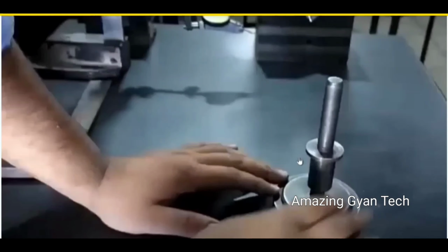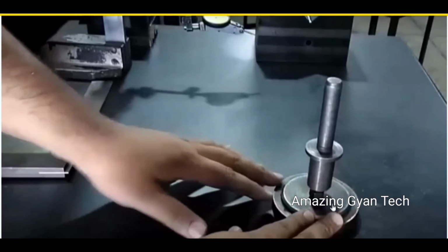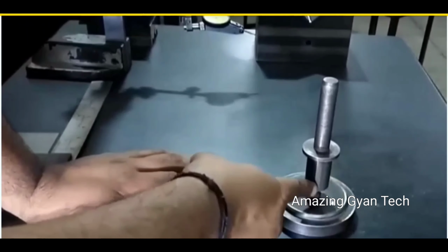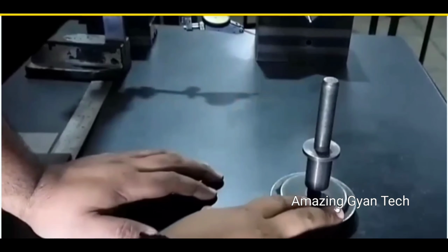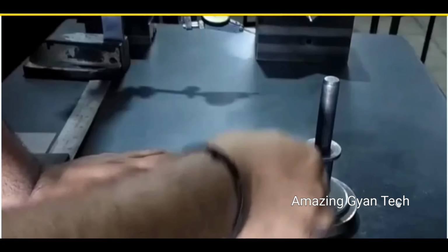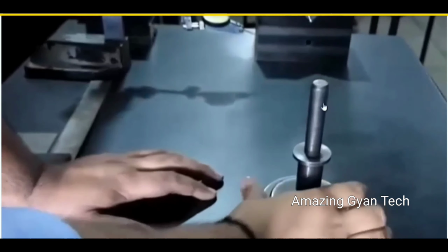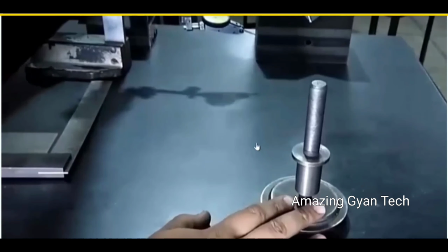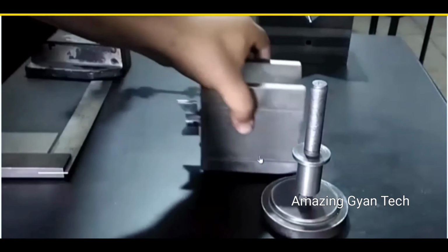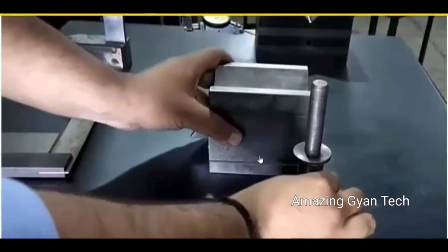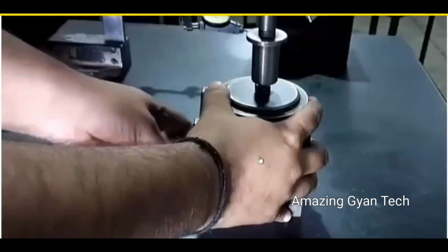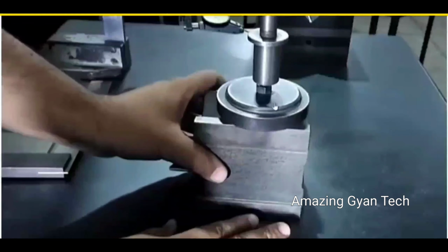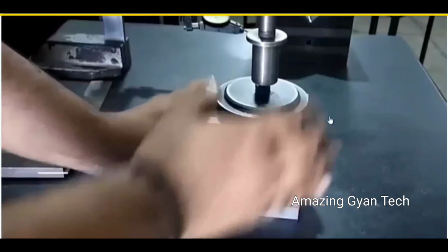If you look into this video, they are going to check the perpendicularity with respect to the bottom face towards the vertical rod with respect to the bottom diameter. For this, they are going to keep this component on the V block. They will attach it to the V block and keep it on the surface plate. The V block, as you know, is going to be a 0,0 face. So it will be placed on that one, and it is locked using a magnet so that it will not get disturbed. And now they will use a dial gauge to dial the surface.